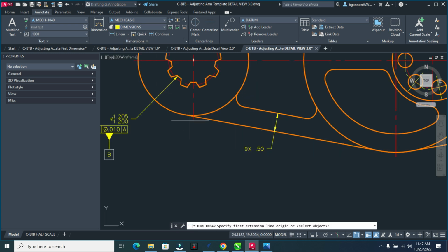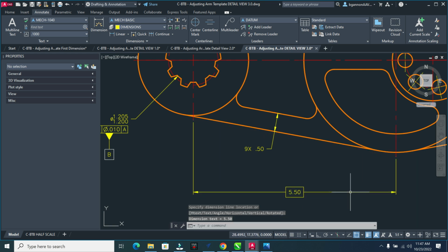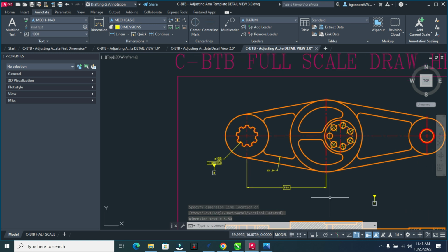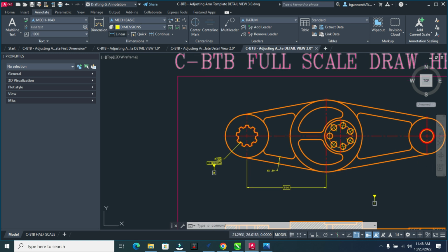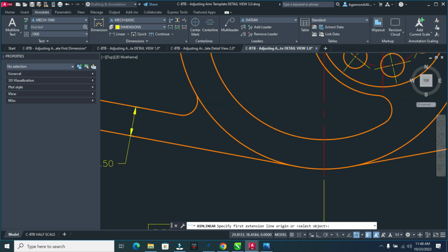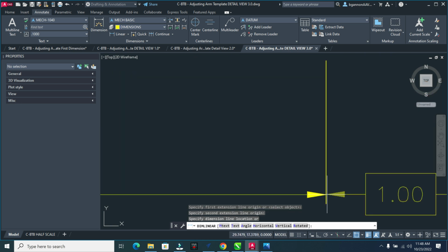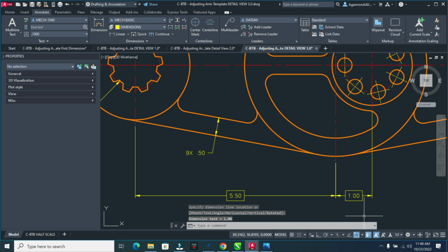And then right here again, bring it out like so. That looks good. Then the next one, to make it linear, I want to make sure I click on the right spot to zoom into it, and then coming up here to right here. Then I can click right in here and it locks it in. Again, these are basic dimensions because they have a square around them.